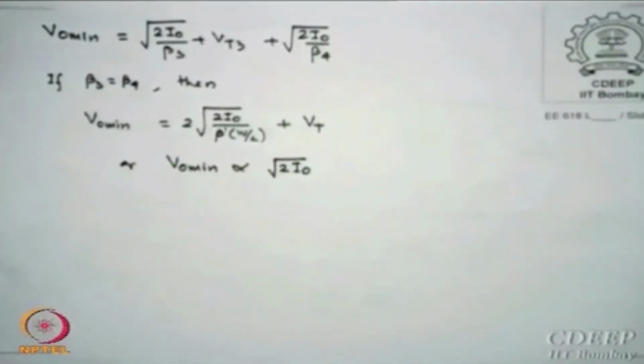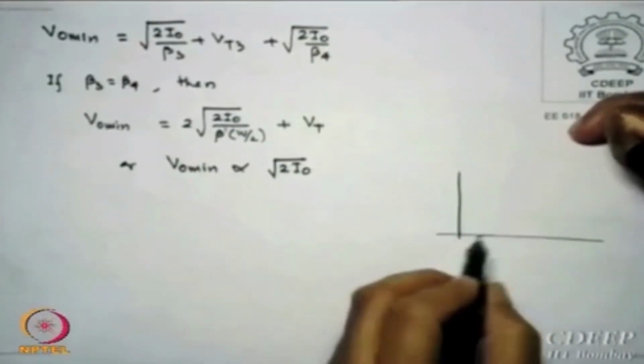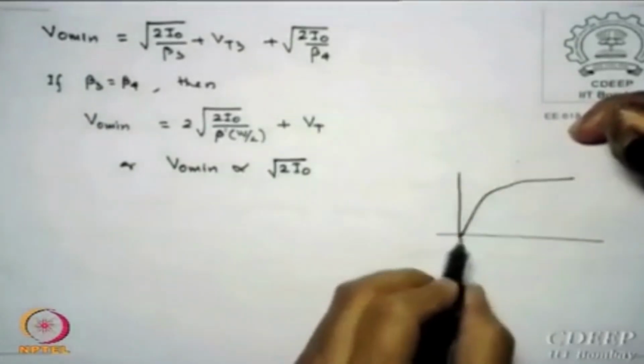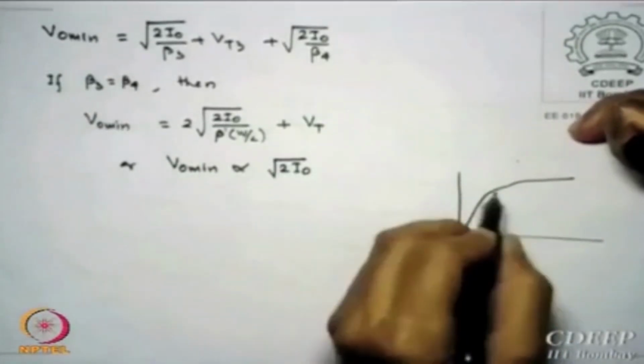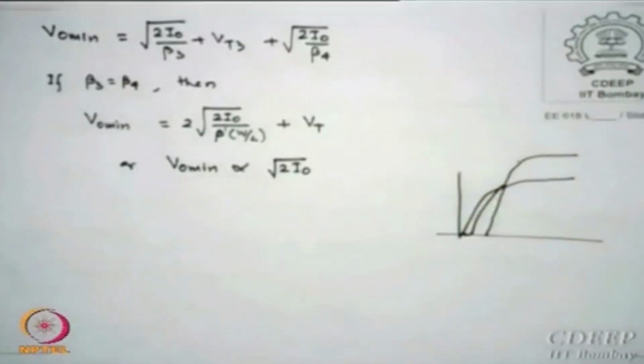So the larger the current source you are getting, by definition or by theory your VO min will increase, is that clear? You can't do much. Essentially I am saying, whatever VO minimum you are getting, if you want higher currents you will have to accept this; there is no other way of pushing higher currents.